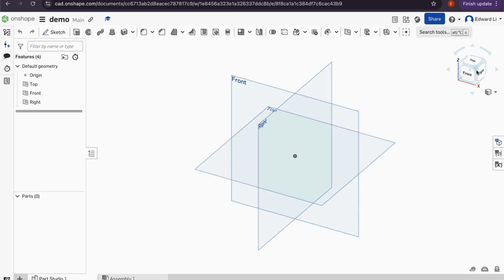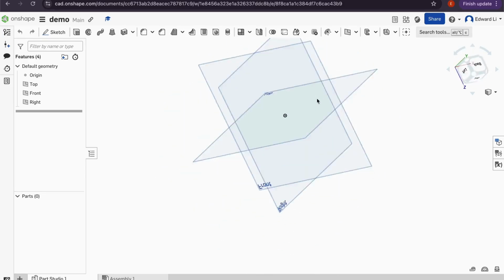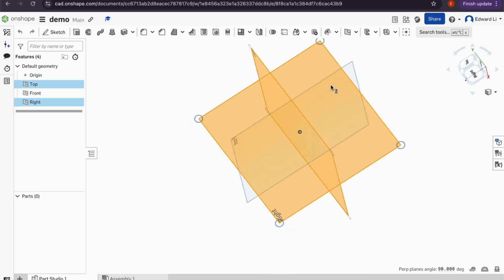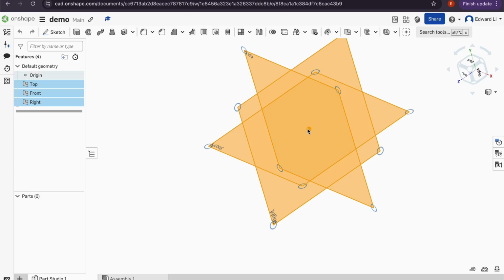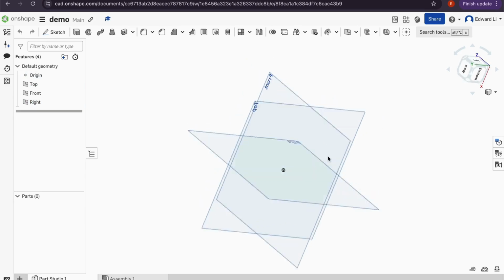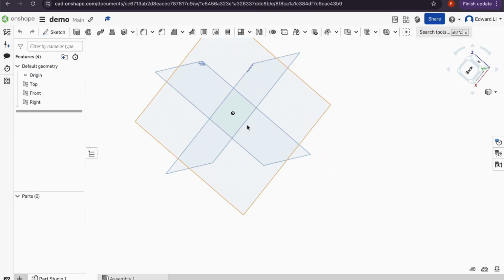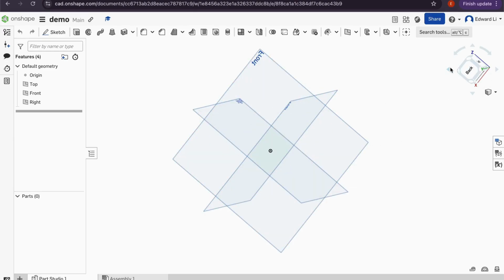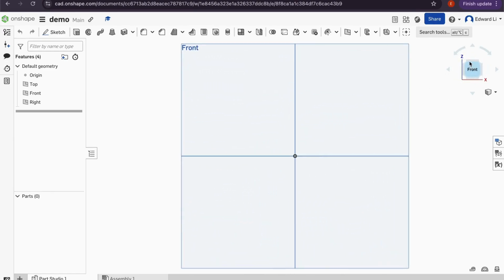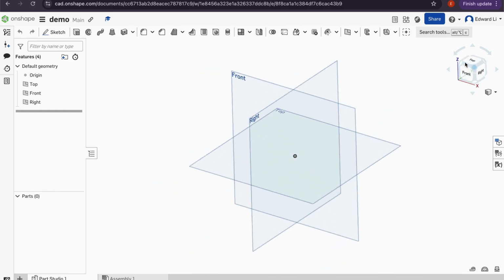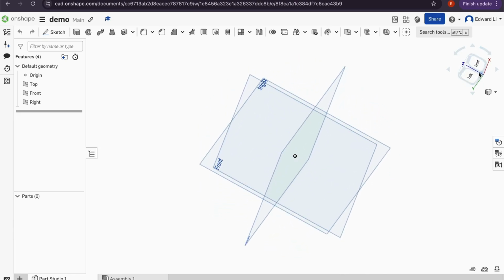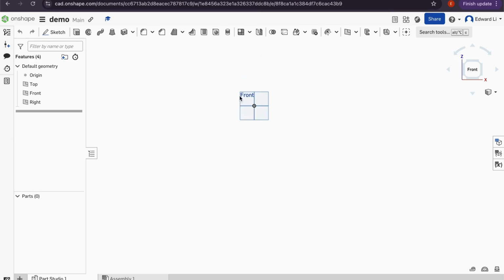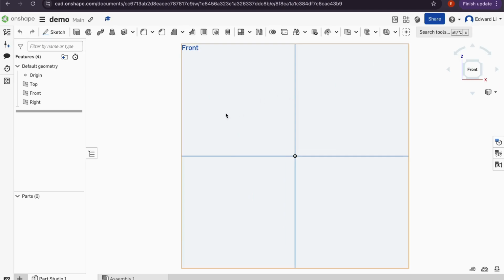Now there's a few basic controls we'll go over. There's right click, which is just drag, to change your point of view. There's click, which you can select something. I'll click these things and then I can select them, or I can click the origin and select it. If I want to unselect them, I can either click them again, or if I want to unselect everything, I'll just click the void and nothing is selected. And then there's also mouse 3, which is just drag it around without changing your point of view. And then there's zoom in, zoom out. After that, there's the view cube, which is just front view, right view, corner view, spin that way. It's easy if you lose track of where you are and you just want to return to base.